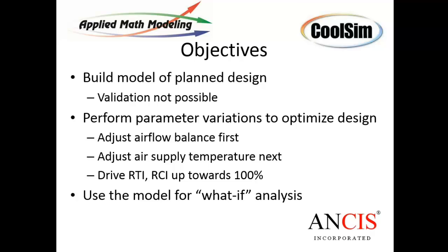In particular, the thing you want to be careful of in data center design is what if a unit fails, or you have to take a cooling unit offline to service it. If that happens, what does the room look like? How does the design perform under various conditions? And by the way, there's more than one air handler in the room typically, so you're going to want to study the failure condition of all of them, all the various combinations, which means you need to make a series of runs, a series of simulations to do that. And those are easily done using a tool like CoolSim.